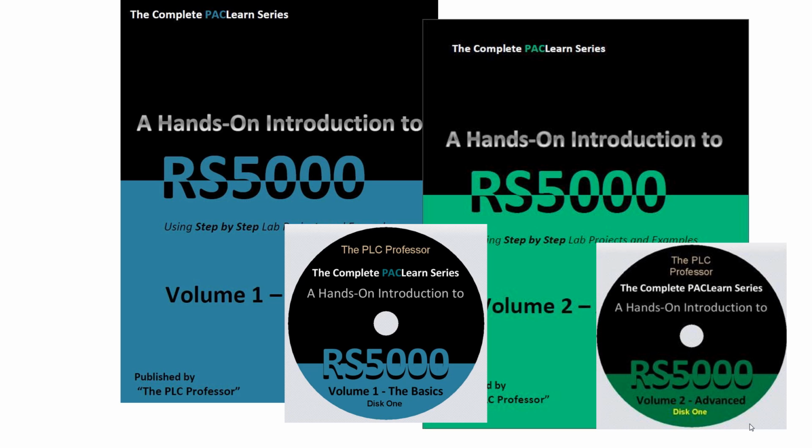So now let's get back to CCW, Connected Components Workbench. At this point you should be able to decide, I'm on the right path, I want to work with CCW, or wait a minute, I might want to start with the MicroLogix. Now, if you're new into the PLC field and you landed on CCW with a Micro800 because it looked cheap, you're going to spend a lot more time learning PLCs with CCW and the Micro800 than you will just paying the money for the not free software for MicroStarter that programs the MicroLogix 1400.